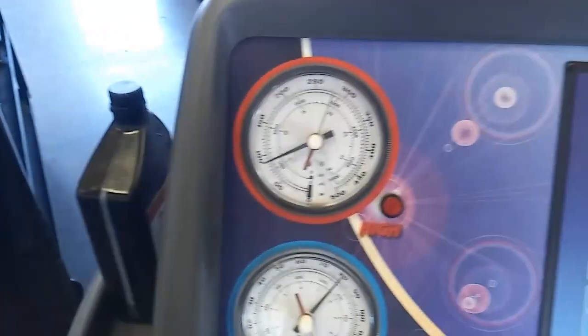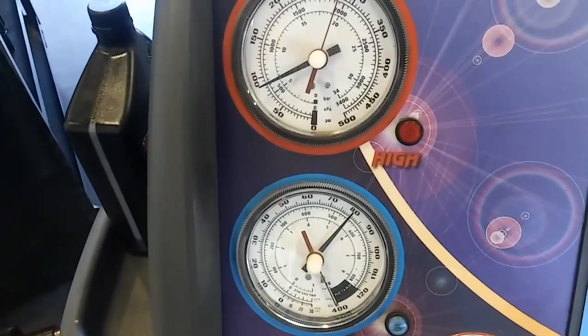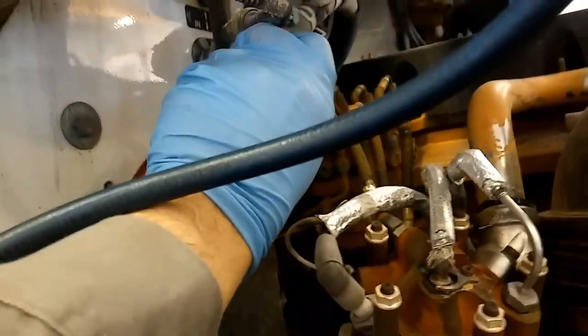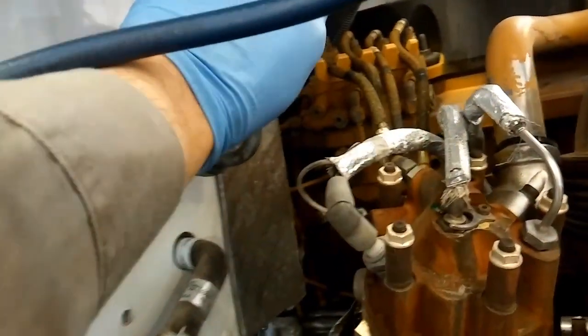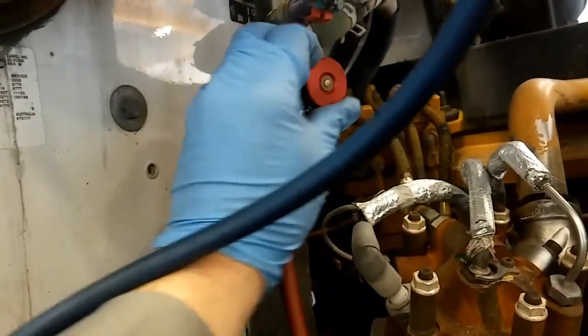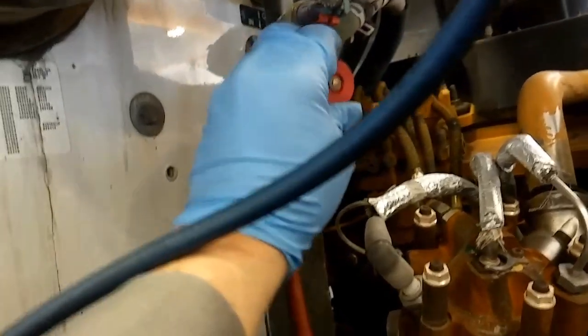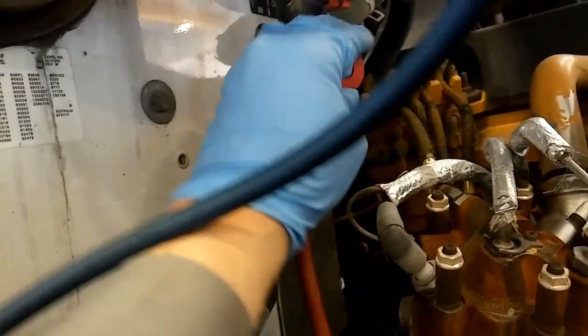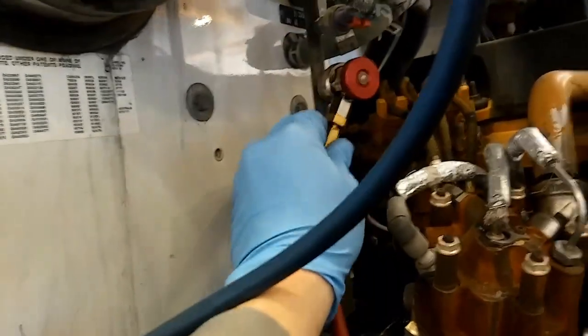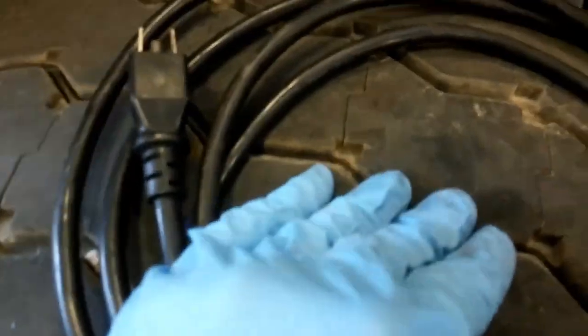Even though refrigerant is fairly cheap, it's considered an ozone depleting element. So you can't really just dump it out. If you crack the line, all the pressure is going to bleed out. So what we use is AC machines to recover it. Now, if the system has a big leak and all the refrigerant is out of it, well, at that point, you don't have to worry about recovering anything. So really, you'll just need your gauges and a vacuum pump of some sort. They're fairly cheap online.